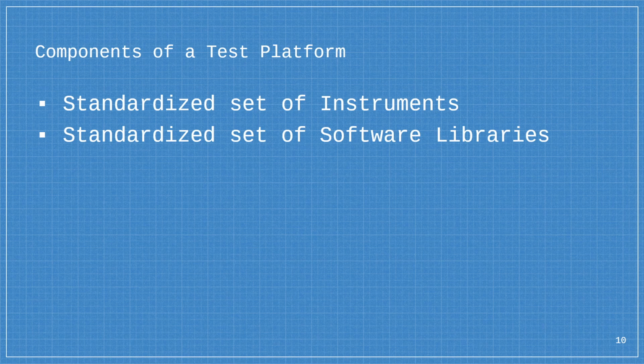So for instance, for a resistance measurement, you may need to measure resistance on channel 1 and return the result. But you don't care if it's an Agilent DMM or if it's a Keithley DMM, as long as both of them have the capability to do that. So the more you can keep it at that level, so you have a DMM instrument class, and in your test sequence, you just call the archetype or the parent class,